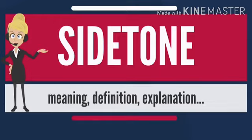In wireless telegraphy (WT) and amateur radio, side tone is the audible indication of a continuous wave (CW) signal as the operator sends Morse code. As in telephony, side tone serves as feedback to the operator that what they are sending is what is intended. It is designed to mimic the tone generated by a typical radio receiver when a CW signal is converted to the intermediate frequency (IF), then mixed with the beat frequency oscillator (BFO) frequency to generate a difference frequency, which is audible over the radio receiver loudspeaker or headphones.